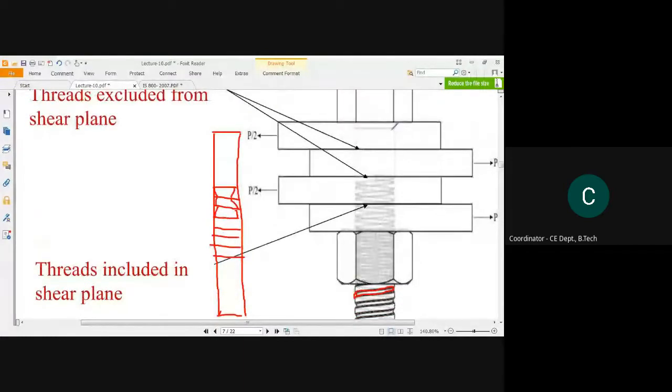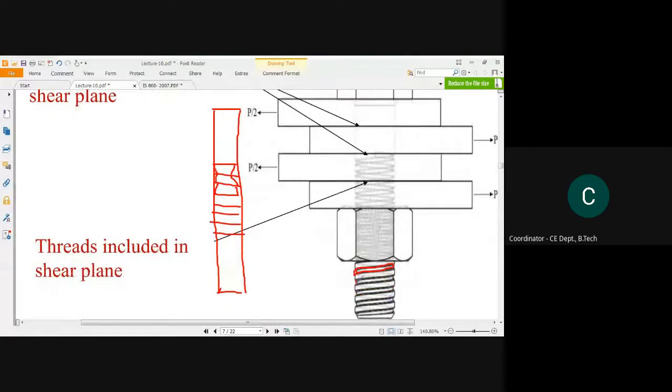from the shank part. So the area is getting reduced when a plate lies in this threaded part, when stress is equal to P by A. So when the area is reduced, the force per area will be increased, the stress will be increased, right? So the same amount of force taken by this plane part will be some amount, but that same force, when it goes through this plate, the stress will be increased.